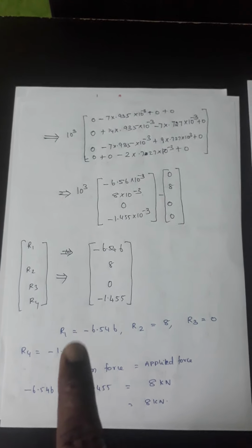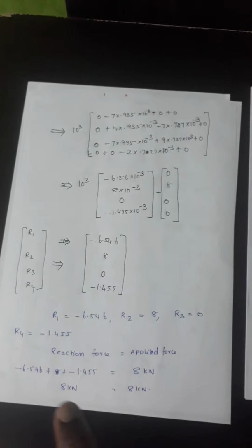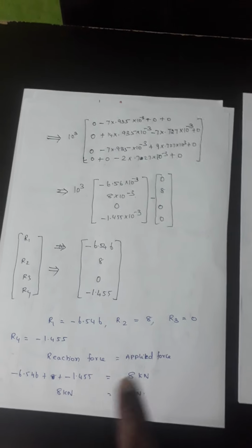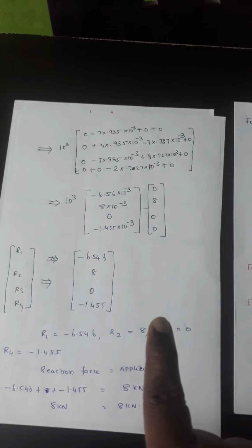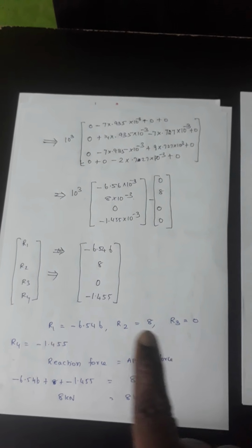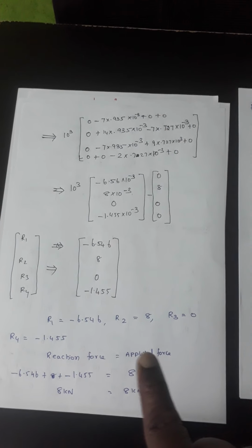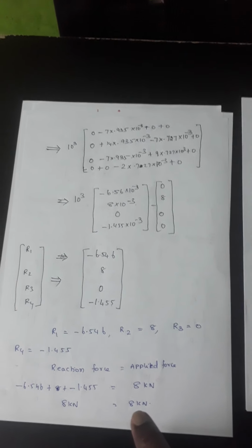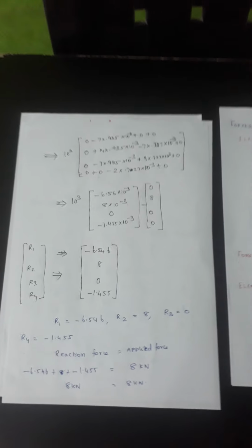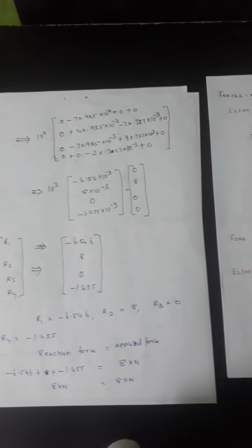The reactions at the supports must be equivalent to this 8. Is it? Yes. So this and this you add, and you will get 8 kilonewton, which is equivalent to the applied 8 kilonewton. So this is okay, verification done. The reaction force must be equivalent to the applied force in the opposite sign.